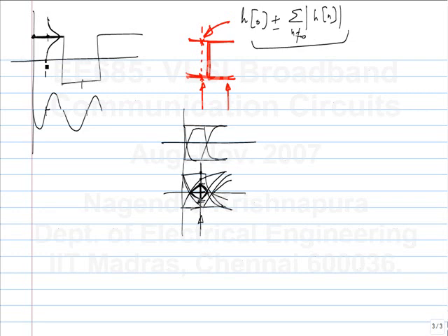What else is possible? The clock, it turns out, can have noise. Normally you want the clock to be perfectly periodic, but in reality it turns out to have some extra stuff, phi of t, which can also be like noise, and this also is modeled with Gaussian noise. So this edge, instead of being here, can be shifted to other values with certain probability, and that probability depends on the variance of this phi.